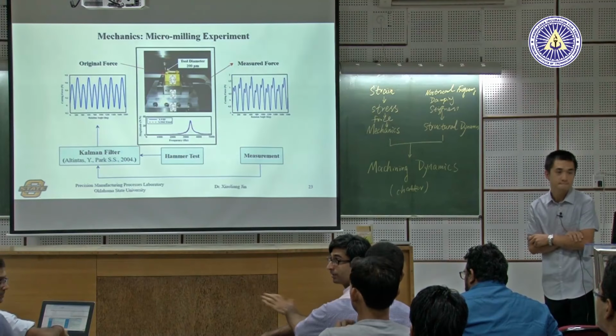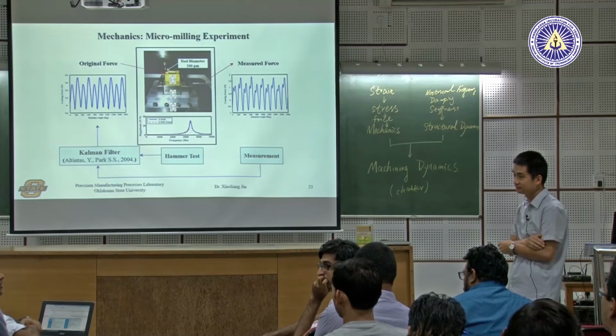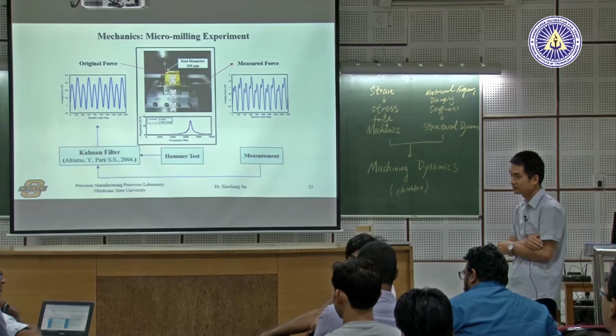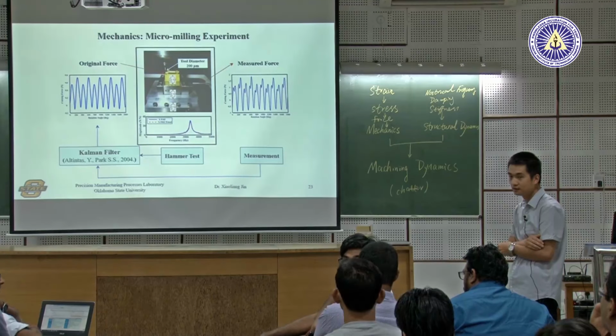Basically, it means 80 micron. If there is runout, the spindle frequency will definitely dominate. Whatever you do, ideally your tooth passing frequency should dominate, because that reflects how much one tooth is cutting. But if there is runout, there will be a very high peak corresponding to the spindle frequency. You saw this, right? That is not a healthy situation, so you are not cutting right. Your machine is not. But is it in your hand, if you're using an end mill? Again, you forget about the spindle.